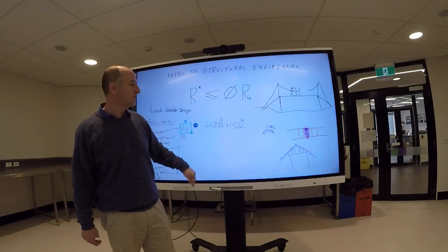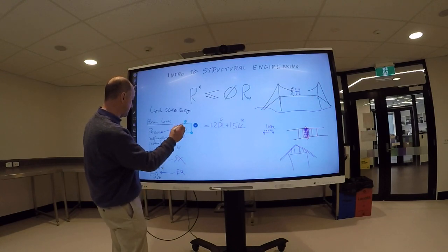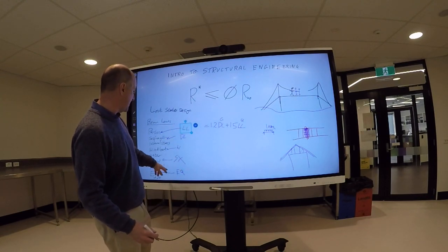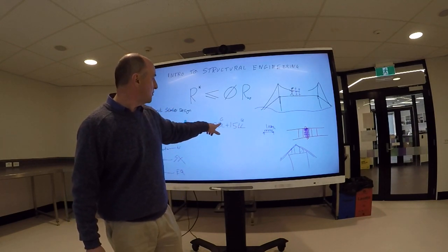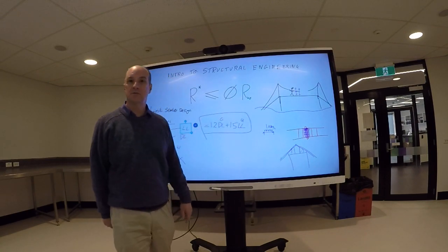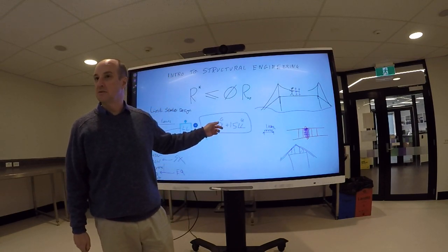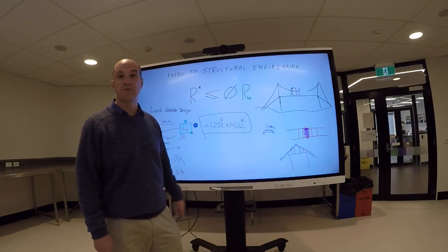And wind, we'll talk about the wind ultimate load, and you can add these other things to it later. So that's an equation you should probably commit to memory. You'll use that a lot. On any particular thing, 1.2 times the dead load plus 1.5 times the live load.